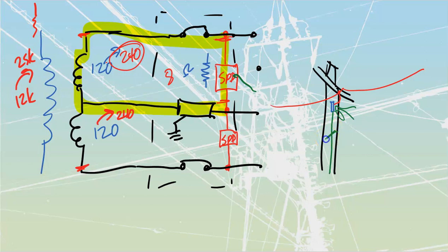If somebody were to open it, cut this thing away, they would be exposing themselves to high values of potential voltage. Not a lot of current, but they could be exposing themselves to 25 or 12 kV or whatever my distribution lines are at that place. So we see these on the side of poles. They're designed to have a trickle of current going through all the time. And then when lightning strikes, boom, it's going to travel through this to ground because that's going to break over really quickly.